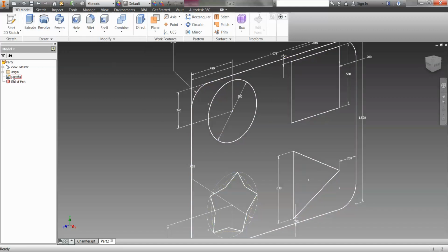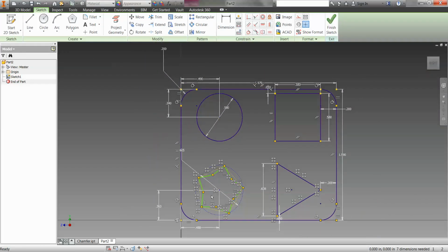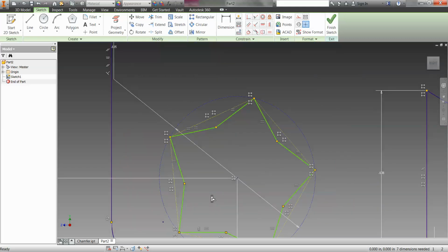So let's go back to our sketch. And this is one of the things that you have to do occasionally, just making sure that everything is working out all right. So I think what I'm going to try here is, instead of equals, we're going to create a slightly different constraint. We're going to delete these equals, and we're going to actually create some more construction lines here. I'm going to put my circle back in place and drag it out to where it's touching on there.